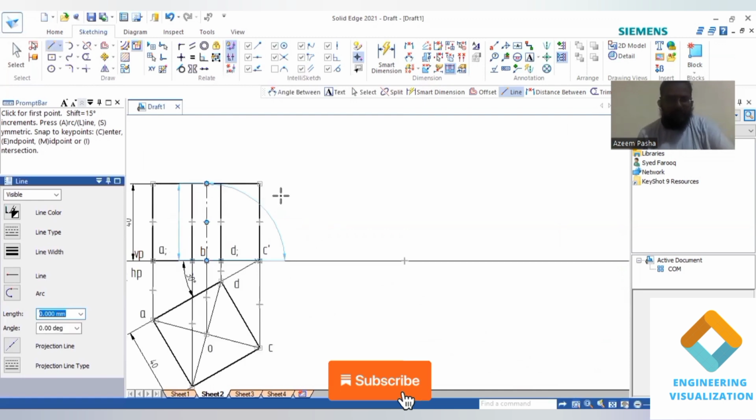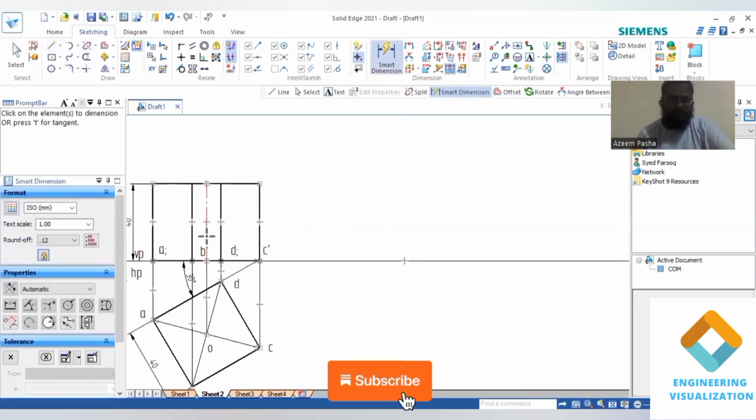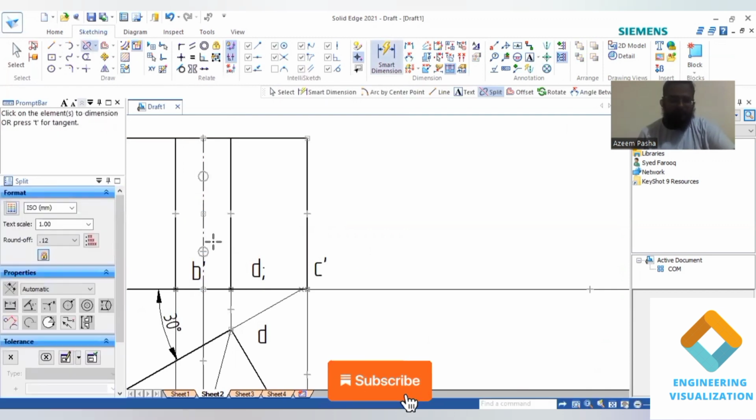Now exactly at the midpoint I'll be splitting this axis line, because we have to draw an angle line exactly at the middle point of it. So we need to split it exactly at the half here. Use the split command, click on the axis and click on the midpoint. So it will get split into two halves. You can choose the dimension for the lower part, so it will be exactly 20 mm.